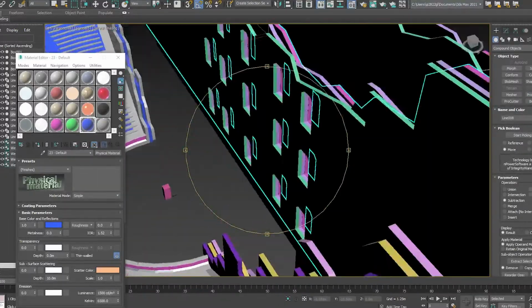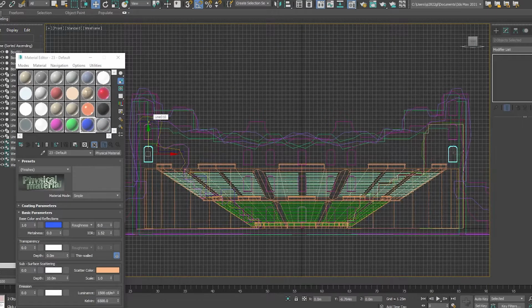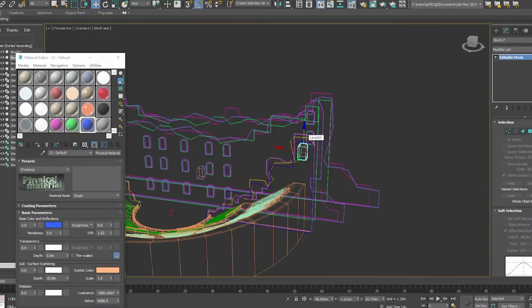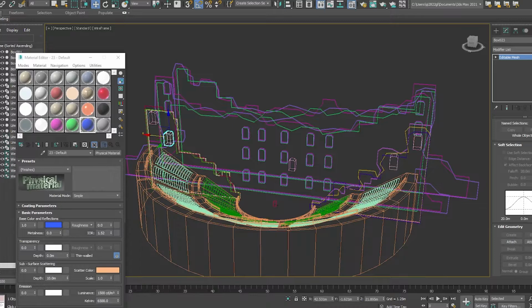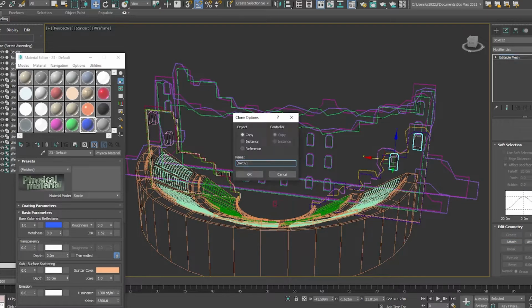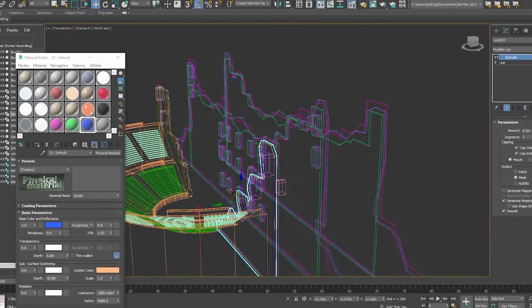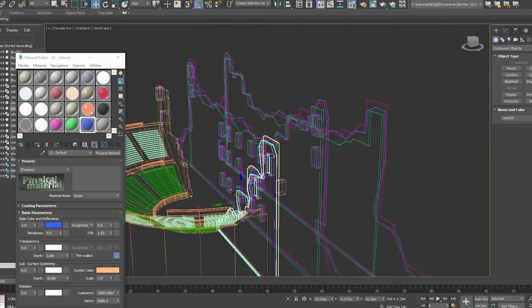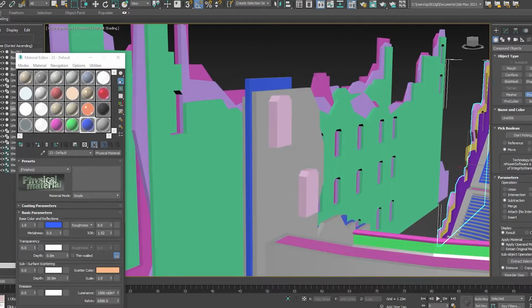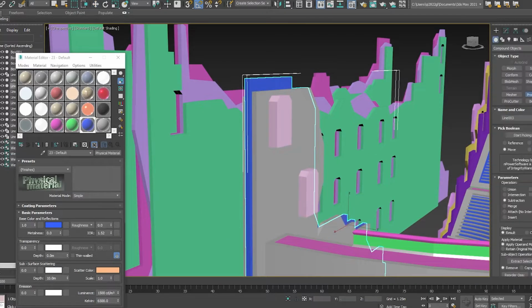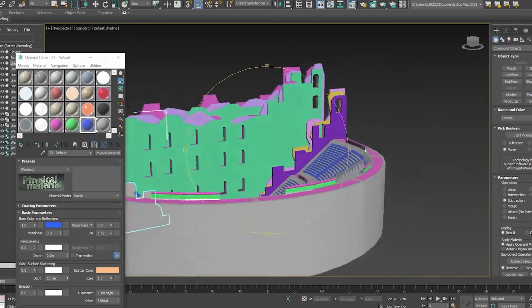So now I've done a Boolean subtraction through each one of these different wall sections, or it looks like I'm still doing Boolean subtractions through each of these different wall sections. Only the bottom row of that first wall is really going to be functional, I think. It's not like this space is going to be used for big productions where actors are going to have to be coming in from different parts of the stage. I think it's pretty much going to be a presentation space for the large part. So only that bottom row of doors into that backstage area, I think, really need to be functional.